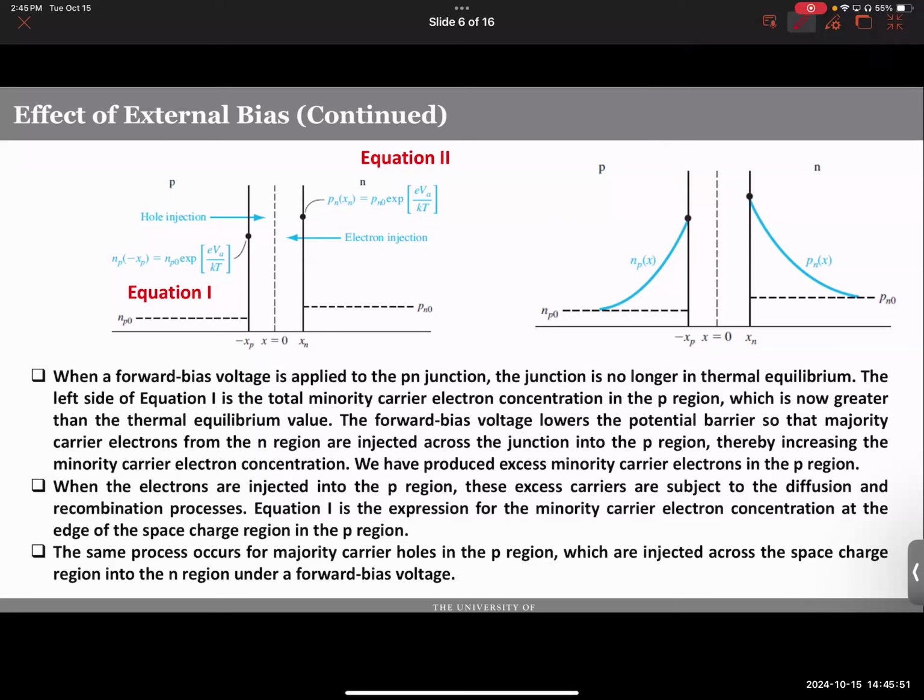And I told you that this might sound disjoint without any subsequent discussions on it, but these diagrams will be instrumental and actually crucial to understand bipolar junction transistors. So there we'll add one more thing to it, because a bipolar junction transistor will have NPN and PNP, one more layer. And the interaction between this diminishing concentration of minority carriers will be a key aspect of the device principle. Okay, so just making you aware of this concept.